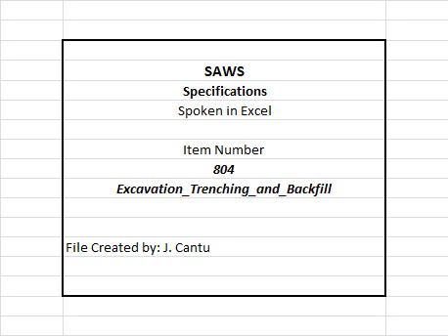804.7 Quality control. 1. All testing to be coordinated 48 hours in advance with SAWS inspector. 2. Samples to be taken in conjunction with SAWS samples at same time and location. 3. Contractor to be prepared to test if coordinated with inspector. 4. Quality assurance testing. The owner shall have such tests and inspections as he may desire performed by a nationally